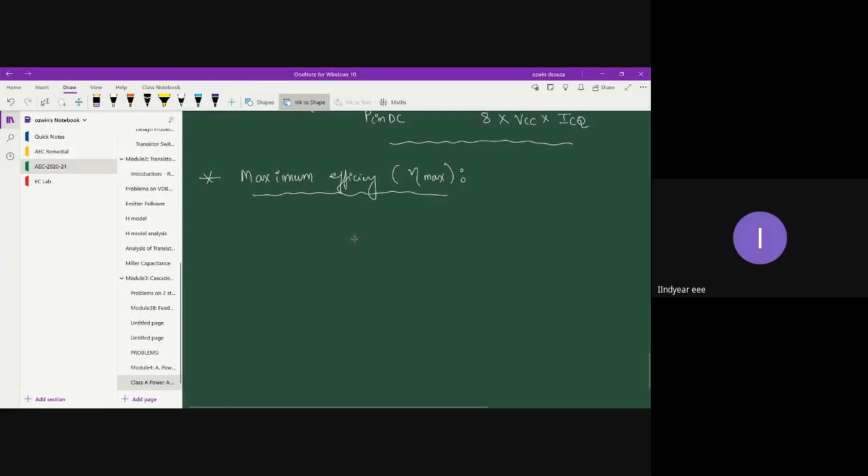Let me please take some time to reconstruct the load line characteristics. I'm not going to draw the output characteristics, I'm just going to draw the load line, that's all. Let me draw it on a bigger scale. Say this is your load line. So this is your IC saturation, and this is your VCE saturation, and your X variable is VCE and Y variable is IC.